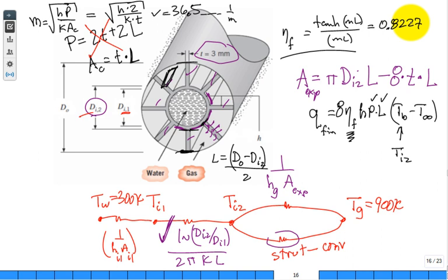All right. So I calculated this, the h was given, the perimeter times the length. Again, we look at the perimeter. Hold it. This is area convection. I need to go slow here. The area convection would be this L here, which is the length of the fin, multiplied by the length going down, and then you have two sides. So you have two, because I used L up here, right?